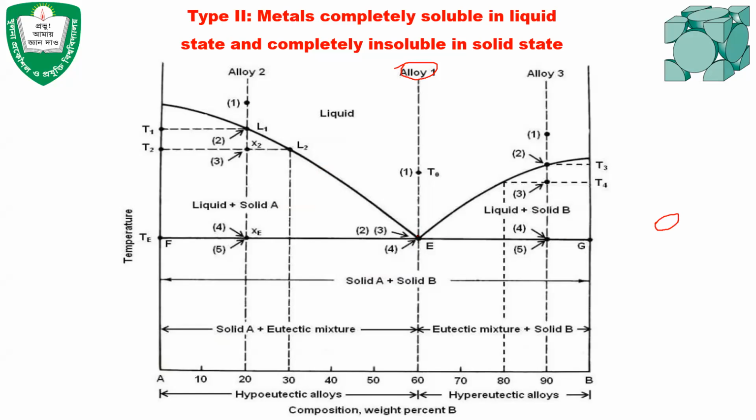Okay, so this is true in the case of all alloys, but the temperature that I was talking about, the eutectic temperature, occurs at the eutectic composition. We remember that it will be necessary for all other investigations, like all other alloys if we want to investigate. So it means that whenever the composition of the liquid is 60B40A, then the solidification will occur at a constant temperature, and that is the eutectic temperature.